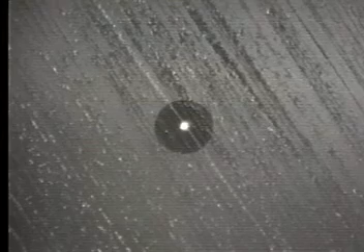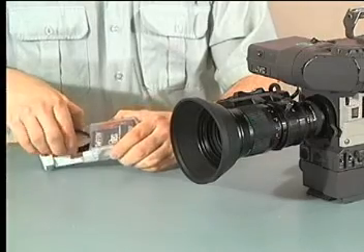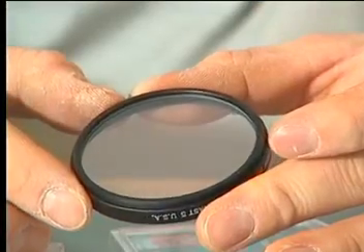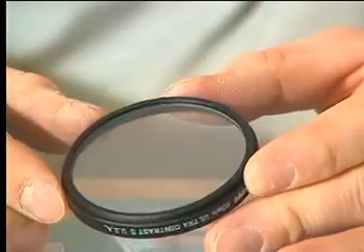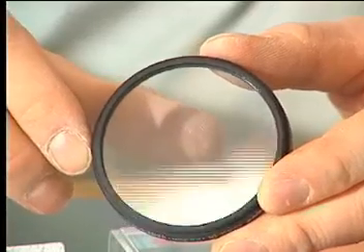This effect is identical to the process used in soft focus filters for photography. The filters use an ultra-thin particulate layer to scatter light rays from the bright spots in a scene. Although sometimes useful in photography, the effect can be disastrous in a fiber optic connector, especially in a DWDM system.